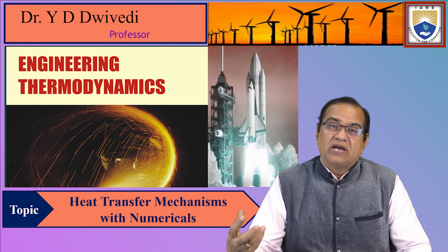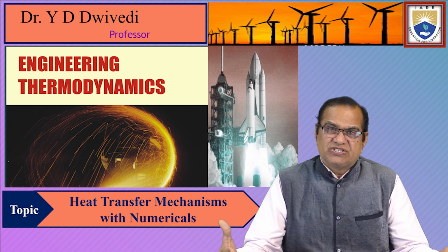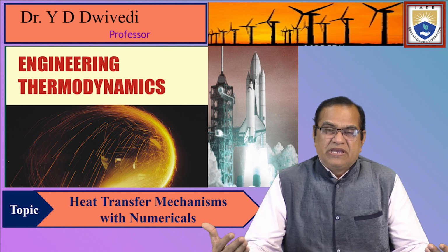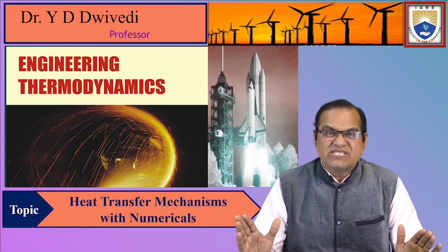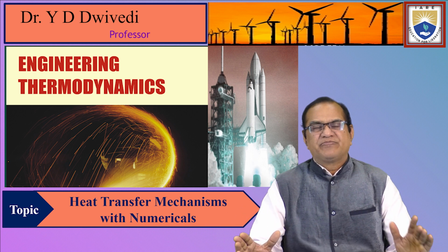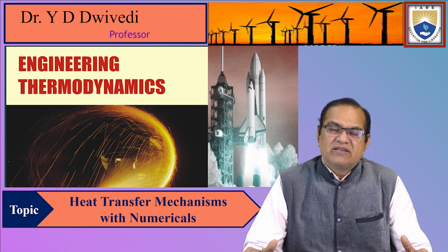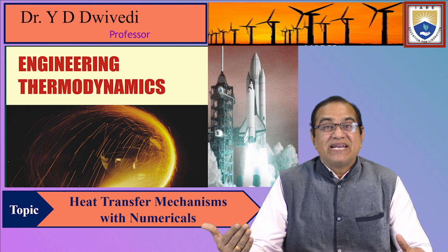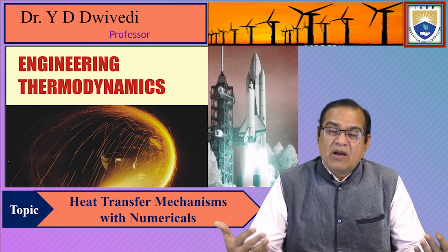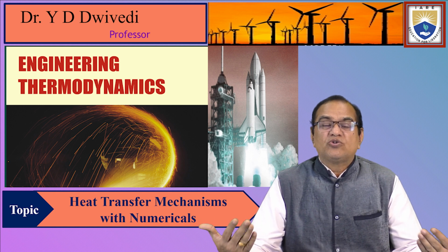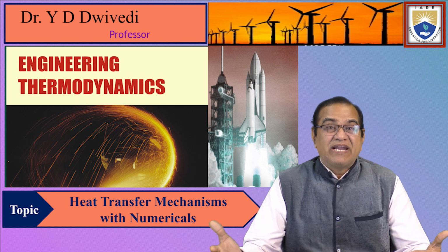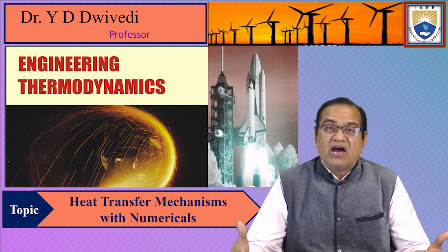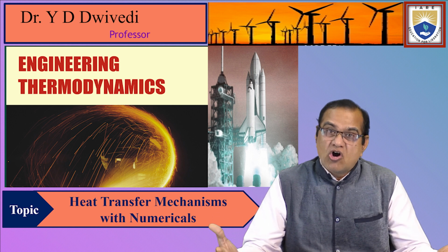Whenever we design any thermal system or engines or heat exchangers or any turbine compressors and all, we should always keep in mind that the ideal case will be when the processes are taking place ideally. It means if it is a compression and expansion, they should be reversible adiabatic or isentropic processes, and other processes may be isothermal, isobaric or isochoric.